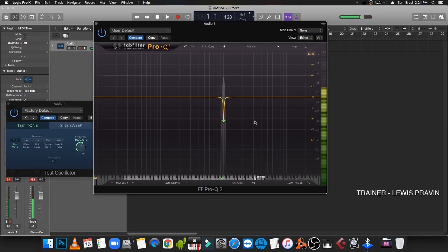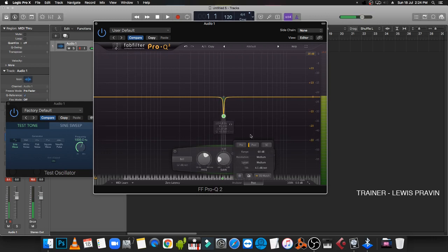In this mode, you are seeing the graph previous to the equalization. That is, you are directly monitoring the input. Now, if I choose post and take off the pre, you are actually monitoring the signal that is post the equalizer. As I reduce, you can see the peak becomes lower and lower. So the graph displays the signal that is post, after the equalizer.